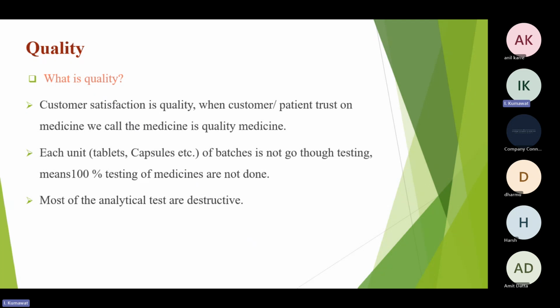Most of the analytical tests are destructive. What does it mean? Once we collect the sample from the manufacturing area for testing, or test it in the manufacturing area itself, like the disintegration test or the friability test of the tablets, that particular sample of tablets we cannot use for further commercialization or further activities.